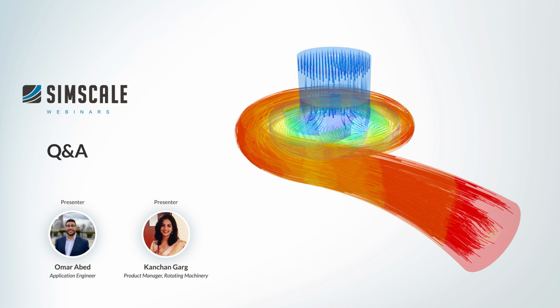Sure, yeah. So working with Fusion 360, that's definitely supported. A lot of different CAD native formats are actually supported. So Inventor and Fusion 360 from the Autodesk suite, SolidWorks, Creo. A lot of file formats are accepted within their CAD native form, but if you're working with a more niche CAD tool that may not be supported natively, you can also export your files to a geometry generic file format. So those are things like SAT, STEP files, IGES files, and the like.